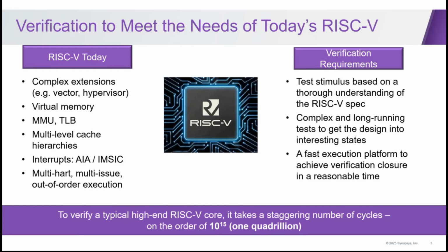But that's a challenge for verification. Introducing cache, L1, L2, system level cache, interrupt, multi-hart, multi-issue, out-of-order execution, all those kind of fancy processor technologies you can see now in current RISC-V design. I will show you in the next slides what a typical RISC-V design we can see from open source.